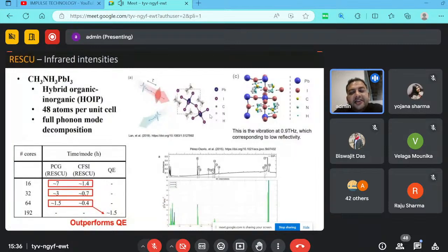So in the coming slides, let's suppose you are working on perovskite material at the material level, not talking about device level. So a perovskite structure is there. The structure may already be available in our database that you can implement, or you can also define your lattice parameters. We have a builder where you can define all your input parameters. For the perovskite materials, you can take hybrid, organic, inorganic materials, and you can make a supercell. You can repeat the structure multiple times and create heterostructures or supercell structures.